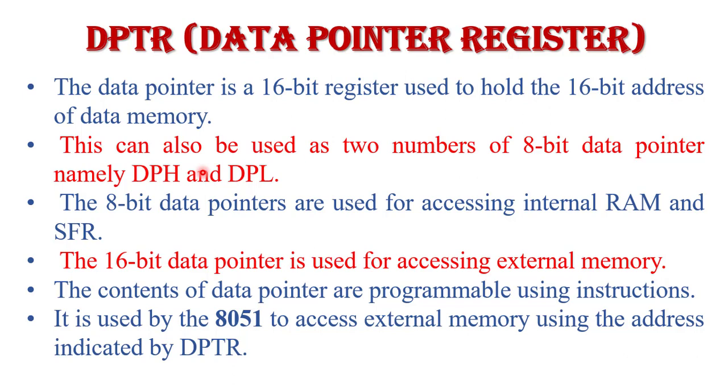This register is physically the combination of the DPH and DPL registers. Both are 8-bit registers in the special function area of internal RAM. The data pointer can be used as a single 16-bit register, and it is also used as two 8-bit registers, that is DPL or DPH. The 8-bit data pointer registers are used for accessing internal RAM and special function registers, whereas the 16-bit data pointer register is used for accessing external memory.